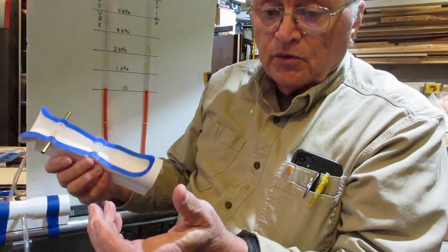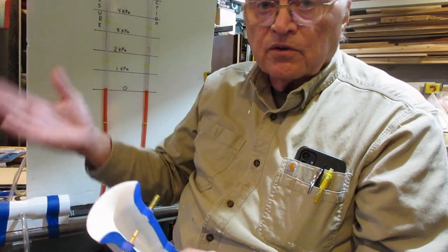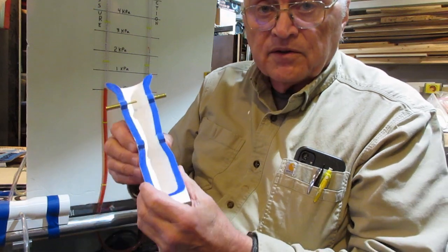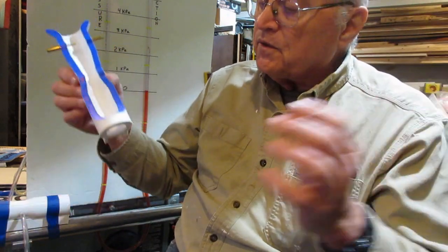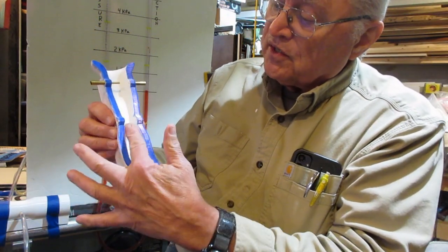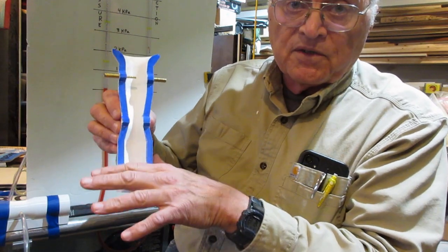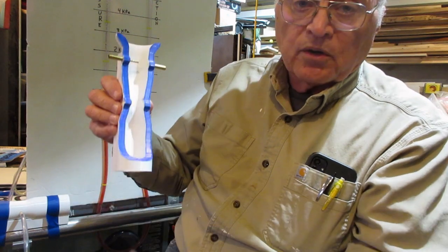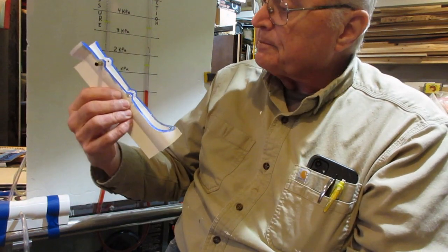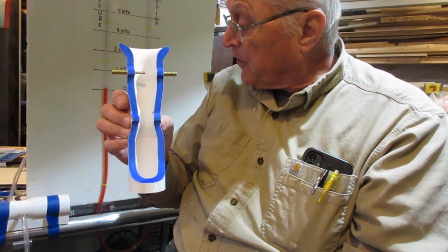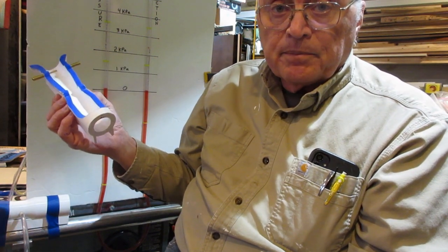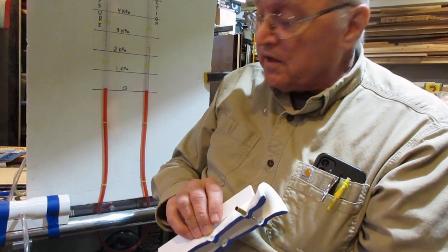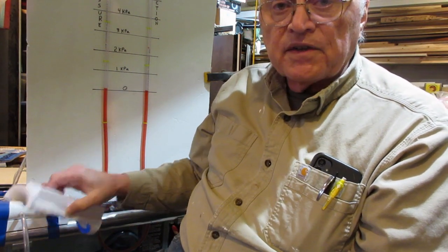You can use just the 2 points, do the math, you can do graphs. It's up to you. And another science project, if you want, would be to explore changing this portion of it to see if you could get better pressure recovery and maintain that same total pressure or close to it further down, okay? So with that, let's fire up our vacuum cleaner and we'll take some measurements on this Venturi right here.